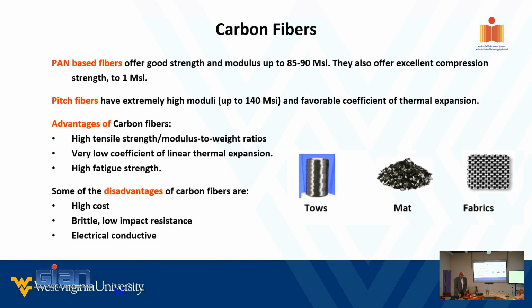Depending on the configuration of the molecular structure, you may have a negative expansion coefficient. When you heat carbon, it shrinks. Not all carbon fibers do, some do. So that is where we juxtapose certain carbon fibers with others to minimize the expansion and contraction coefficients.